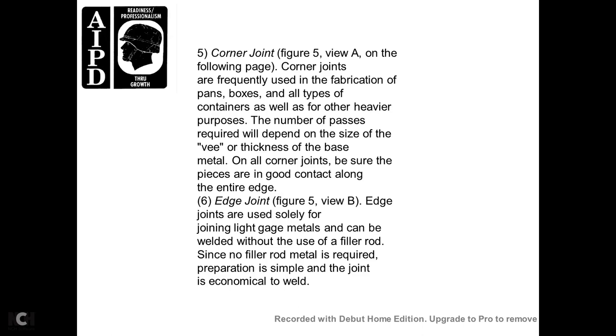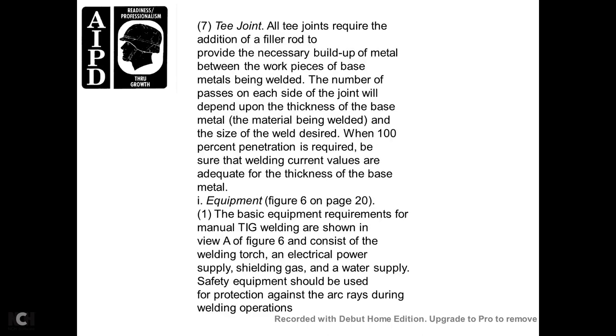The edge joint. Figure 5, view B. Edge joints on light gauge metals can be welded without use of filler metal. Since no filler rod metal is required, penetration is simple and the joint is economically welded.